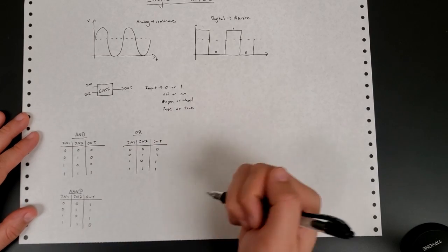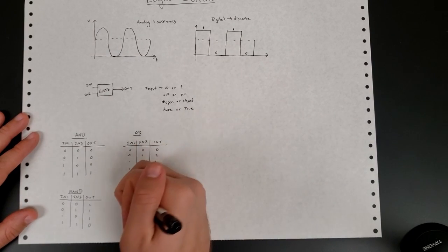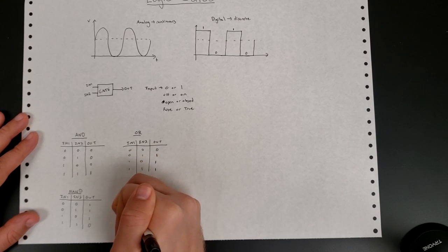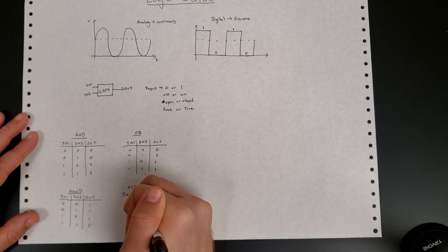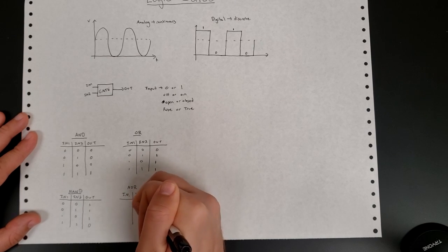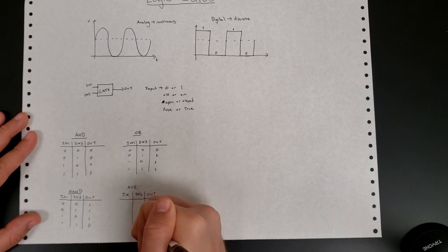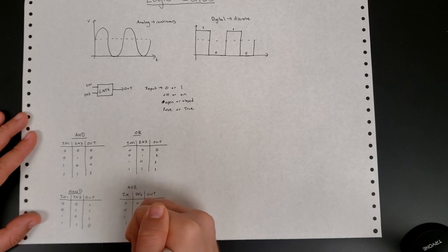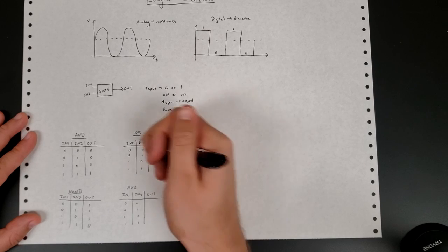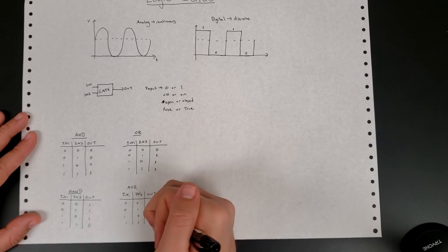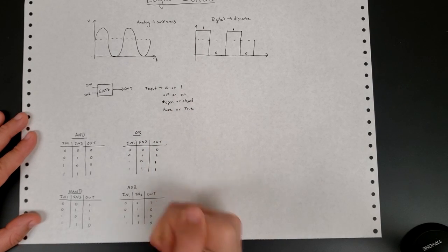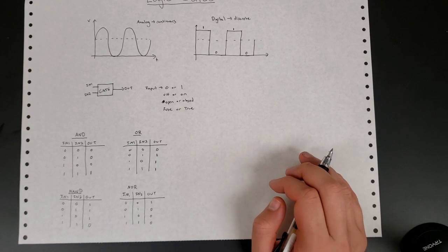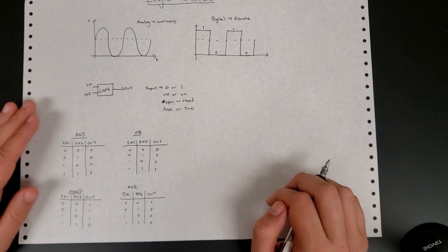And so similar to AND and NAND, you can also have the inverse of OR, which is a NOR gate. Output, where all of these inputs again are the same. And then our output is the opposite of our OR gate. So instead of 0, 1, 1, 1, we get 1, 0, 0, 0. All right, just two more gates to talk about here, and then we'll talk about ways in which we can build some of these gates.